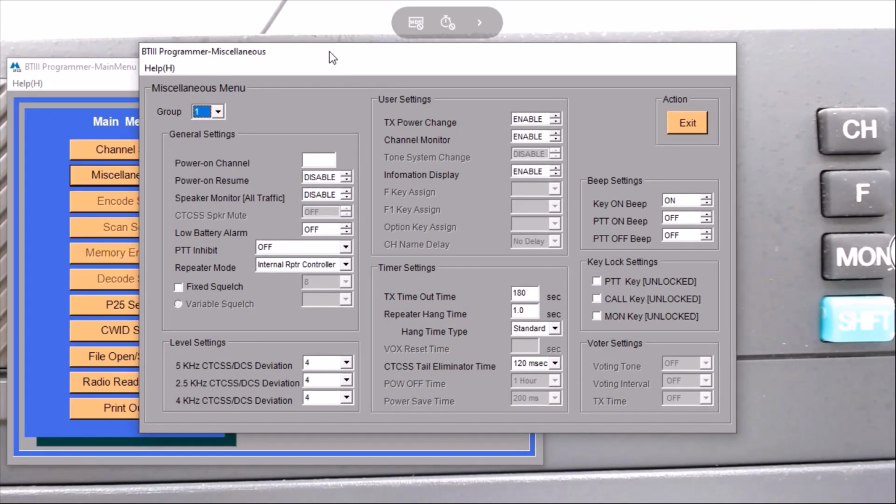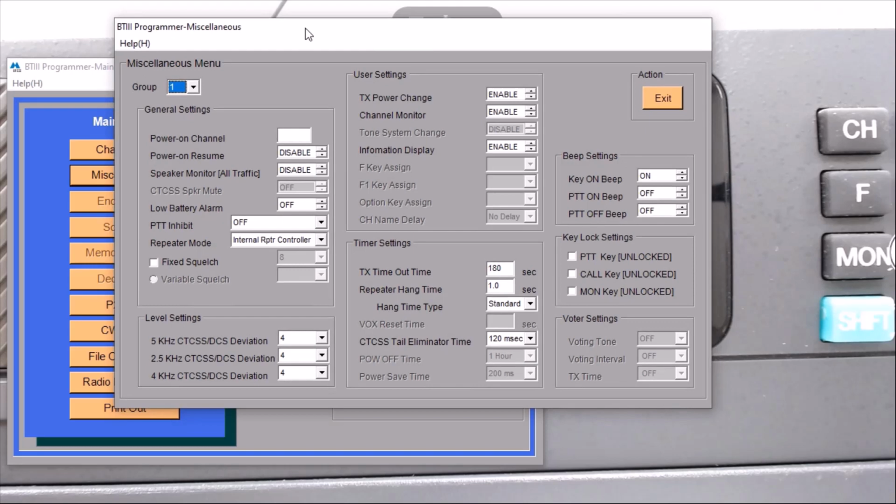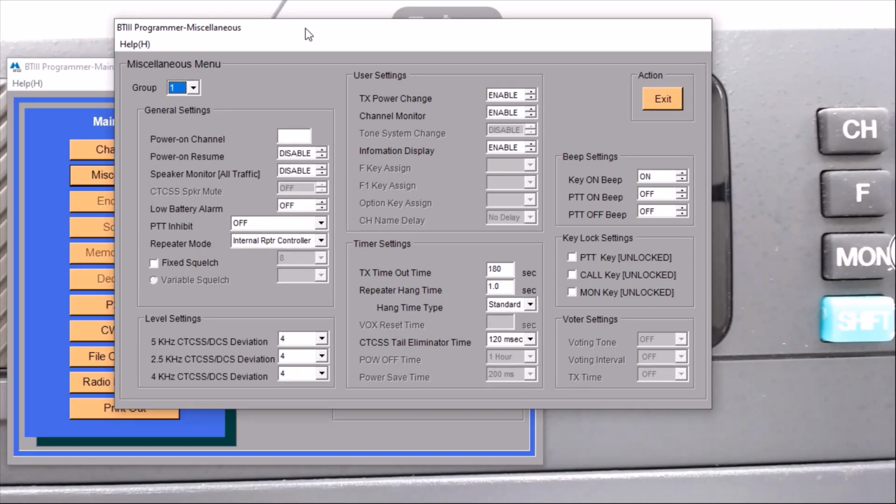Okay. All right. So, in order to adjust the PL and to keep the radio from over deviating, it was kind of a fight back and forth, because the PL is controlled by the voice deviation pot, and also all the physical pots on the transmitter for the PL tones are all disabled. They don't do anything because it's all electronic.